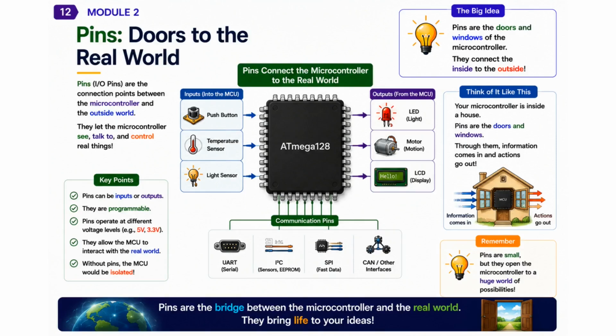One important point to remember is that pins are programmable. We can configure them as inputs or outputs depending on the needs of our application. They also operate at specific voltage levels, such as 3.3 volts or 5 volts. Without pins, the microcontroller would be completely isolated from the real world. It could think and process information, but it would never be able to sense anything or control anything.